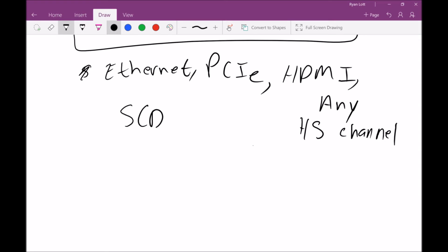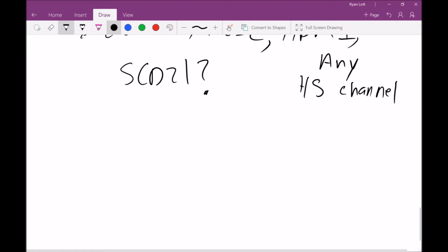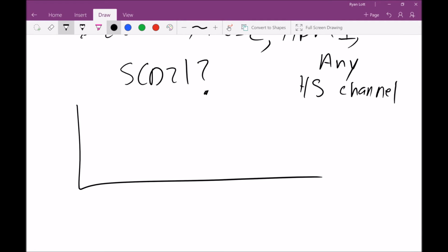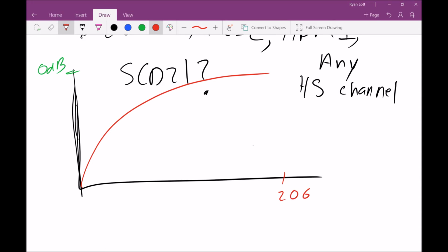SCD21. How high is it? So a lot of times, when you're measuring things such as cables, PCBs, with respect to 0 dB, you might see a PCB over a span of 20 gigahertz. Mode conversion maybe looks like this. In cable, you can see some really funky effects.